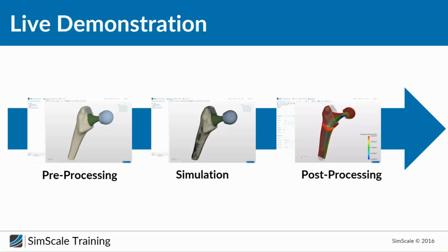The final design sometimes has a lot of details which are not necessarily important for the simulation. To give you a very easy example, just imagine something completely different. You have an airplane and you want to do a fluid aerodynamic simulation of this plane. Then you have, let's say, 20,000 screws on the skin of the surface, but the screws are so small that they will not really affect the overall physics of this phenomenon. So you have to minimize your model as much as possible.